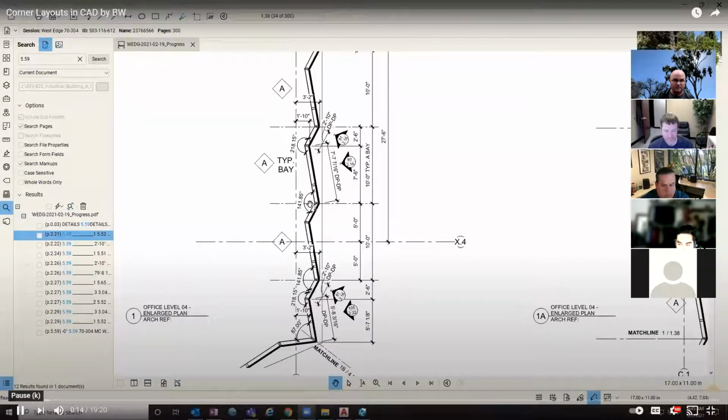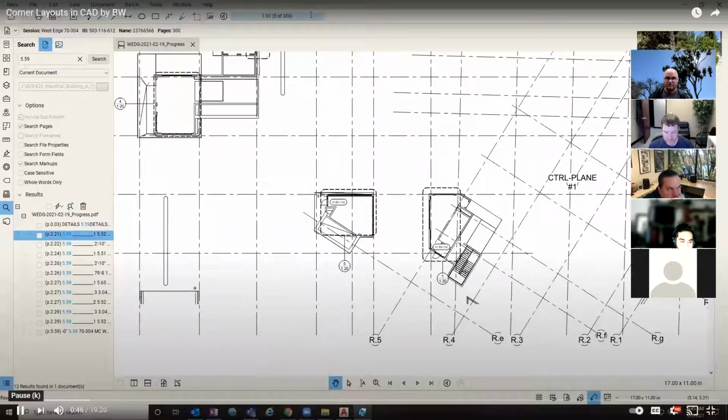Today we're going to take a look at some of the layouts that we're doing on West Edge. We have an articulated type wall where there's a lot of inside and outside corners with various degrees. The mullion pairs are built to the closest degree that we had available if the floor plan angle didn't match an exact existing mullion pair. In some cases, we do have mullion pairs that are matching the floor plan angle, but a lot we're doing some slight layouts too.